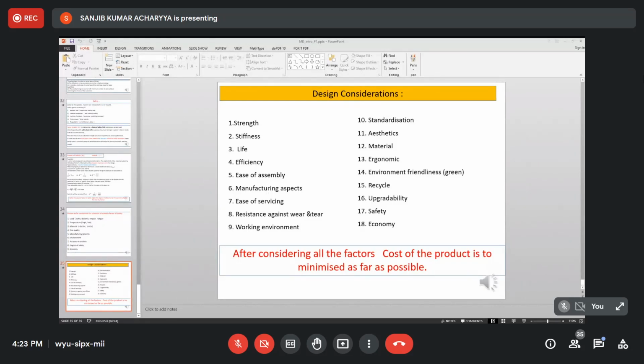If fluidity is low, it is not preferred for casting, because the material, or metal in liquid form, should flow into the intricate details of the molds. So the fluidity of a metal governs whether it is good for casting or not. Similarly, by judging different material properties which are relevant to a particular manufacturing process, the goodness or fitness of that metal regarding that manufacturing process can be estimated and assessed.